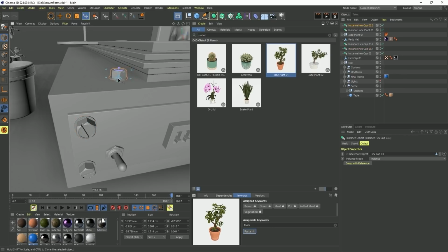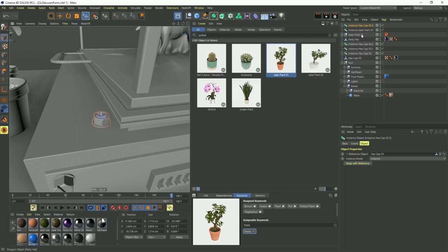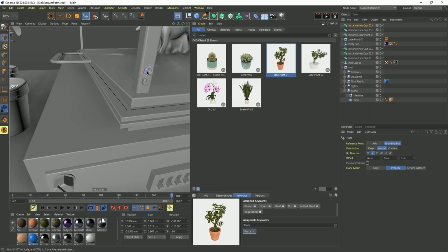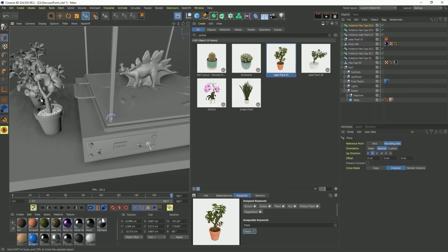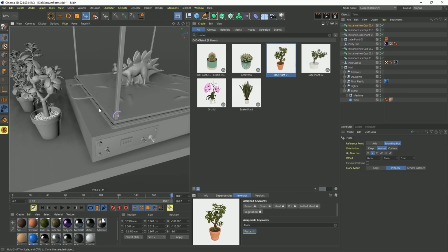And as I drag it, you'll actually see it's going to be, let me turn off collision. As I move this around, you can see it'll travel very specifically along the surface. You can even see it follow the curvature on the edge, jumping to each angle, place it right there, and scale it down. Now we've got a different size, and the copies, of course, will always be based on the previous one. So I can put 2 bolts right there very, very quickly. So I really like the place tool just as a quick go-to for getting things layered in your scene without having to put too much thought into it.